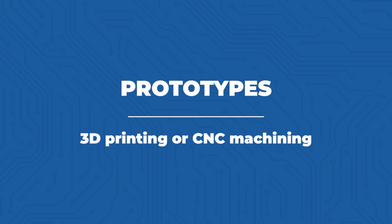So that's something you need to keep in mind: things like the look and feel, the way things snap together, are all impacted by the type of plastic being used. So if the type of plastic is really critical for your product, then you may want to start off with 3D printing, but then eventually transition over to CNC machining. You can get prototypes built that are made using the same plastic that will be used for production.